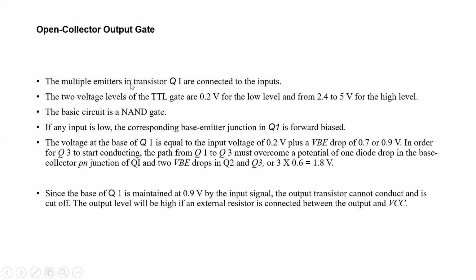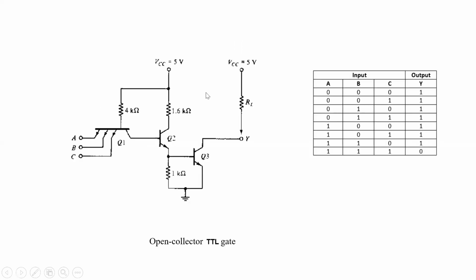This is the transistor Q1. Here the base and collector are single terminals, but the emitter is multi-terminal. Instead of using multiple transistors, we are using a multi-emitter transistor.